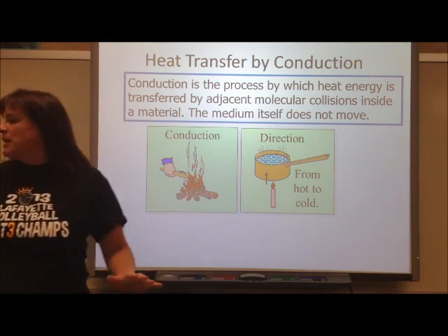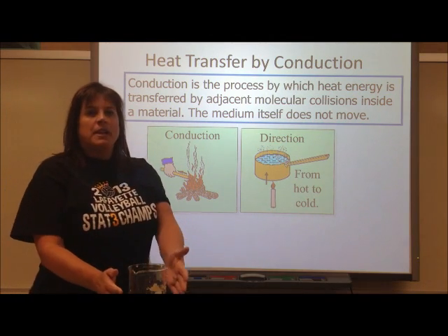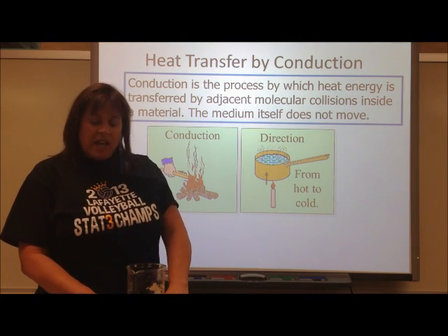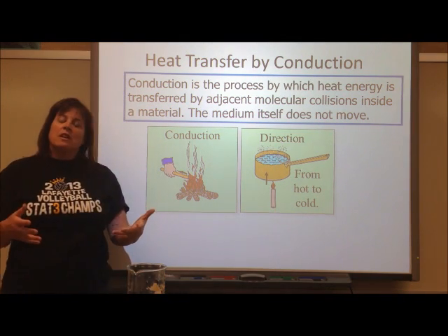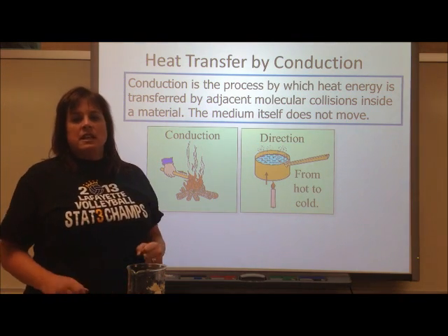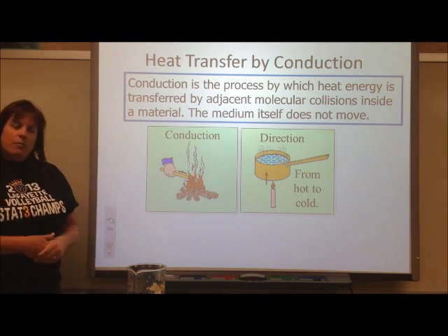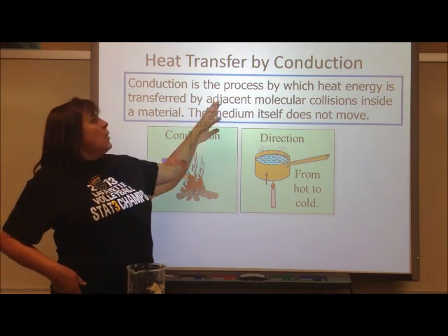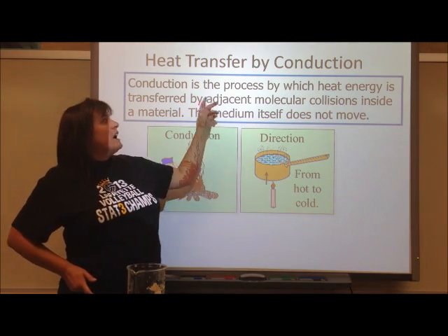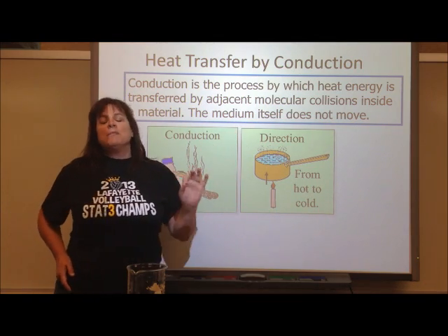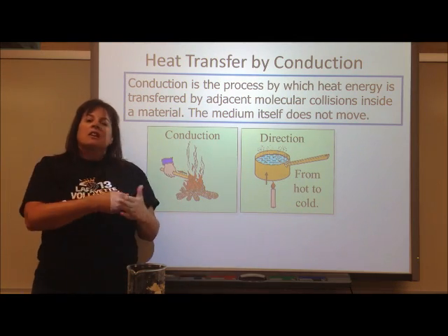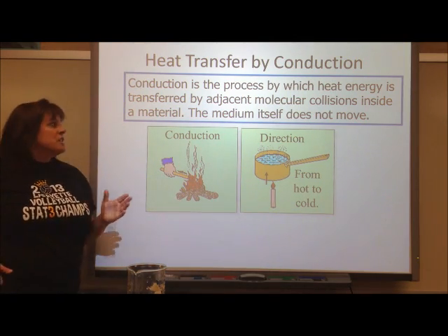If I turn on my hot plate and I put a beaker of water on the hot plate, this is direct contact between the substance I'm heating and the heating coils, and that will result in heat transfer through conduction. Actual collisions between molecules in the heating coil with the beaker, and then the beaker with the molecules of water. So anytime that we have heating by contact, then we have heat transfer through conduction. So the medium itself is not moving. It's the collisions, the bumping into each other, that are actually transferring the energy, heat transfer by conduction.